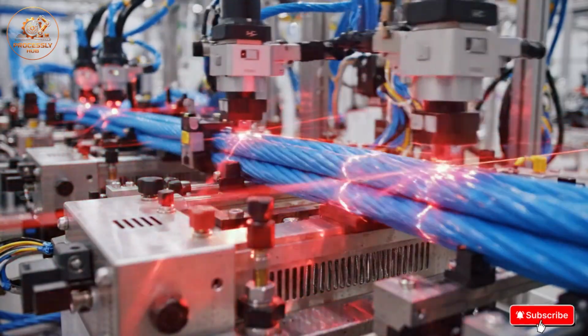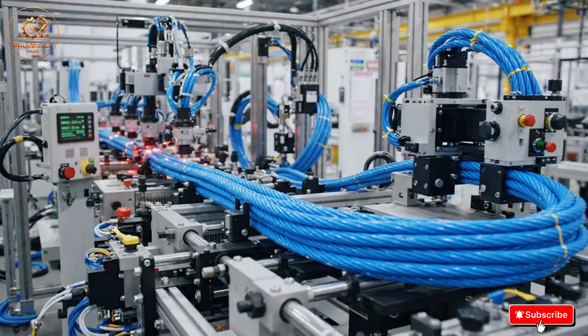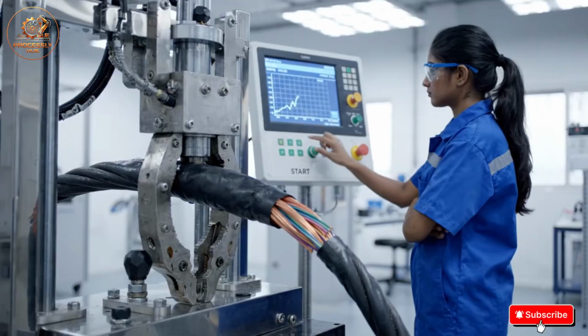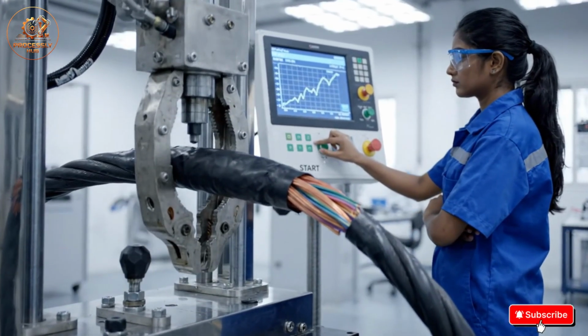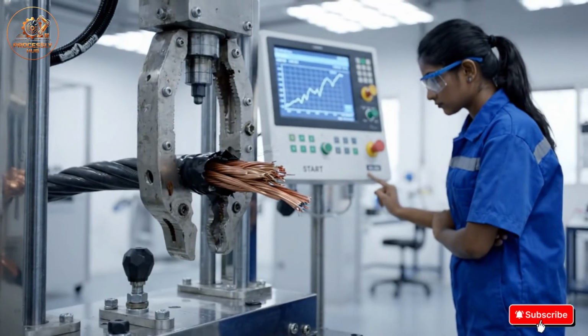Precision instruments verify the cable's dimensions. Consistent size is essential for proper installation. Sample cables undergo tensile testing for mechanical strength. The jacket and conductor must withstand heavy loads.